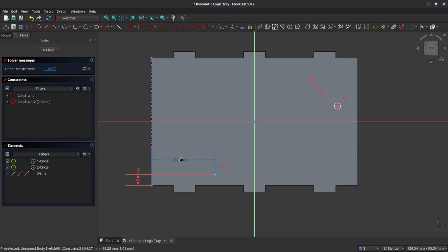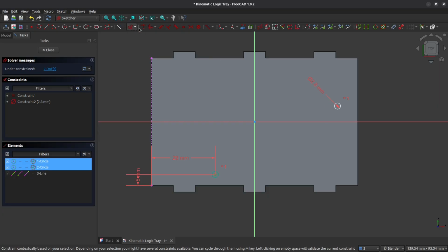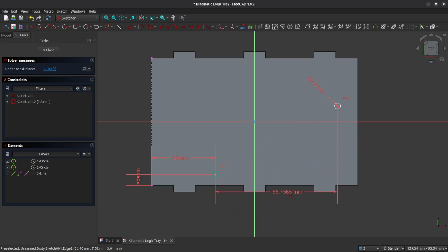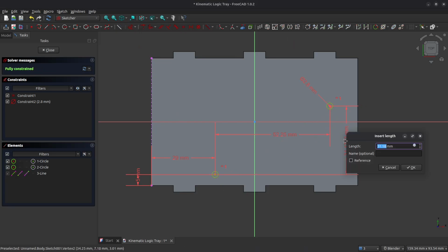So this is the side closest to our front frame rail. Now that we have that one screw there, we're going to position the second screw hole in relation to this first one. These measurements come from the Arduino itself. So I just took a reading off these holes and came up with this set of measurements. Okay, so 52.25 millimeters distance between these holes, and we need to set the vertical offset now between these two holes. That's going to be 32.5 millimeters.